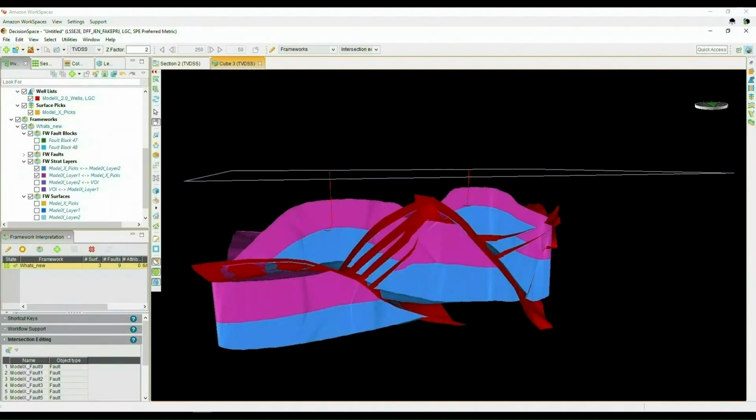This session has a framework which is modeling compressional geology, characterized by reverse faulting. The Complex Geology algorithm deals with multi-Z surfaces by splitting the framework surfaces into individual fault blocks based upon the framework's fault network. Splitting the framework into individual fault blocks allows each block to be calculated discretely, whereby only data points within each sealed fault block are used to calculate the framework surface geometry. This means that repeated stratigraphy can be independently resolved as long as the surfaces are divided by framework faults.